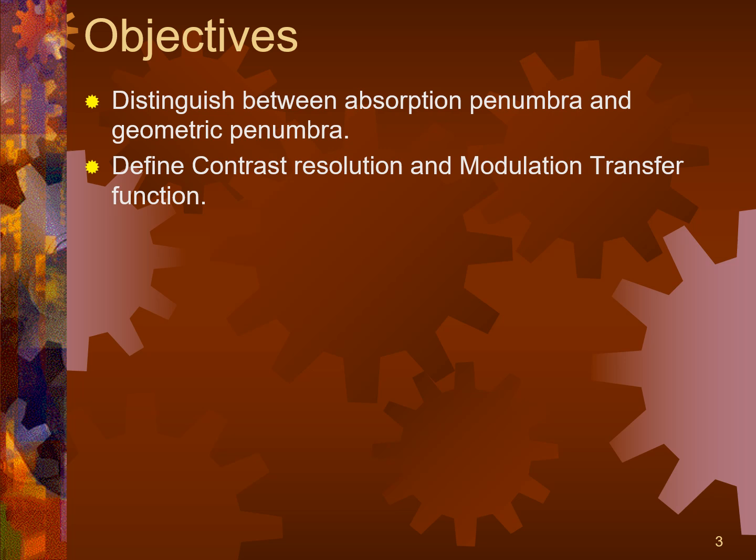Well, high frequency modulation, or high frequencies, are also, yes, we can erase those, but also the pixels are at a certain pixel pitch or pixel size. And so the pixels have a frequency too. And that's where the Nyquist theorem comes in, and that's where modulation transfer function comes in.